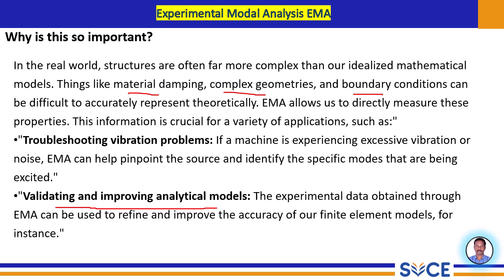FEA is a powerful tool, but its accuracy depends heavily on the quality of the input and the assumptions made. By performing experimental modal analysis on a prototype or an existing structure, we can obtain real-world modal data. This real-world modal data can be compared directly with results from our FEA models.